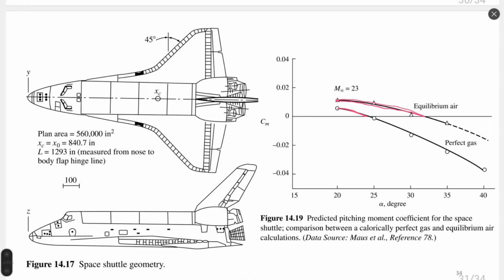It says that to calculate accurately and correctly global aerodynamic characteristics on re-entry vehicles, it is important to use a model of flow which takes into account transformation of gas with respect to temperature, like decomposition, dissociation, recombination, and ionization.